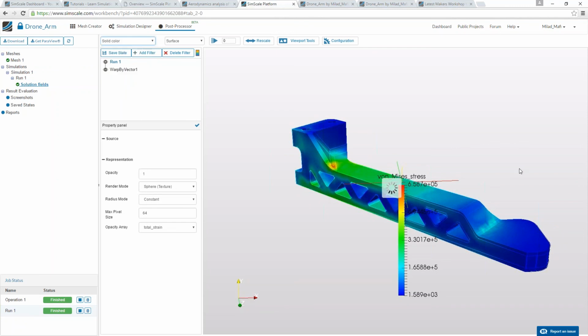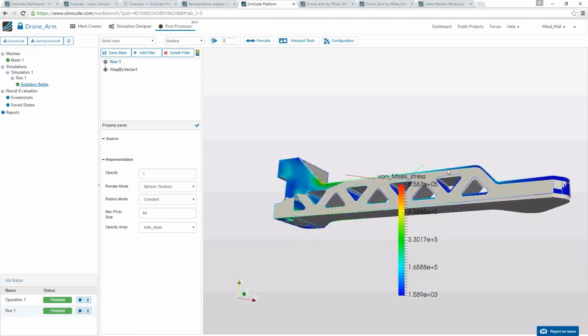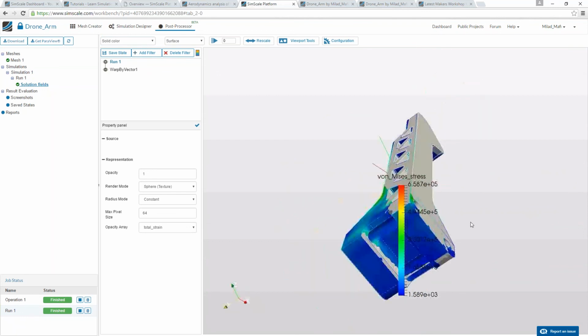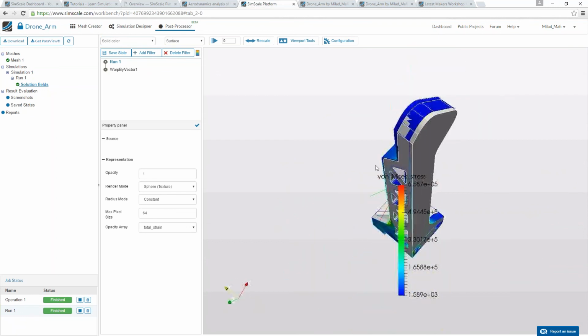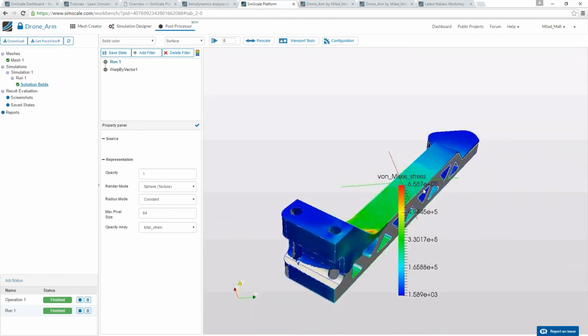And now you can really see here how much the displacement is. So you have a displacement, but I would say it's less than a tenth of a millimeter, so that looks good. And yes, here you can really see it good. The gray one is the original, how it looks at the beginning, and then the colored one is the displacement of this arm.